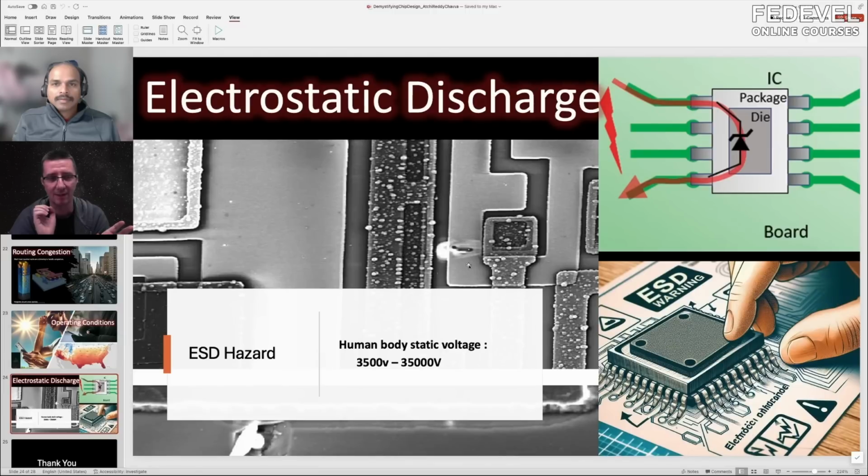I remember in your lab, you're supposed to have everything ESD connected, or ESD discharge connected, the wrist strap. And I was always like, no, I'm not going to do that, because I would like to find out if there is a sensitive chip rather than my customers. Of course, you have to use it in production, when the chips or boards are manufactured. But when I was working in my lab with new boards that I was designing, I was not wearing this stuff, because I wanted to find out if there is something sensitive.